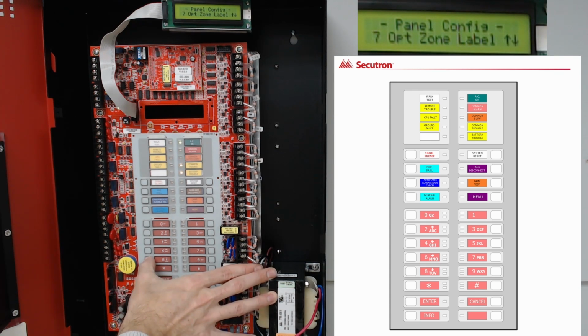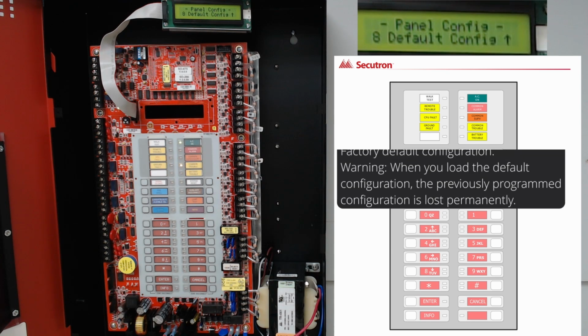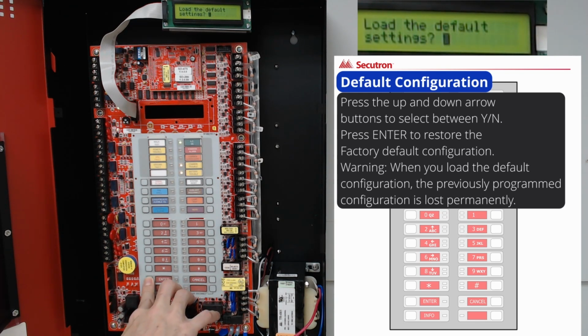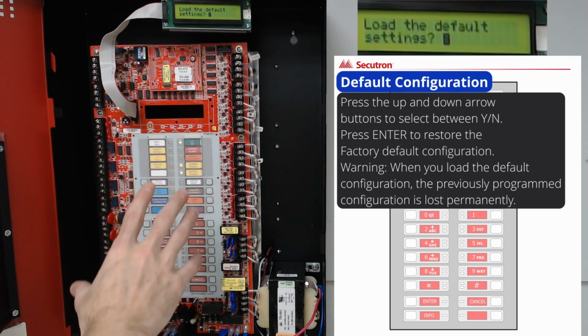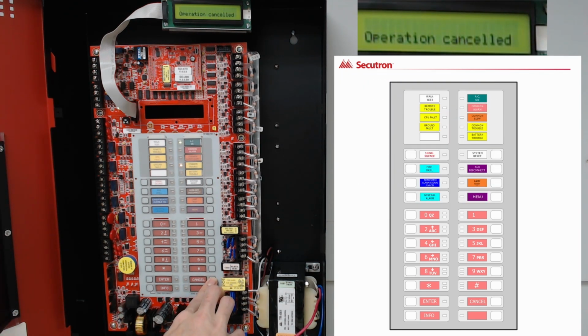Our last option in panel config is default configuration. Use this menu to load a default configuration into the panel. Warning: when you load a default configuration, the previous program configuration will be lost permanently. So please be aware whether or not you truly desire to default your panel's configuration. By selecting yes and hitting enter, anything that you have previously done as far as panel config will be reverted back to its default. By hitting cancel, we can go back out to the panel config options.